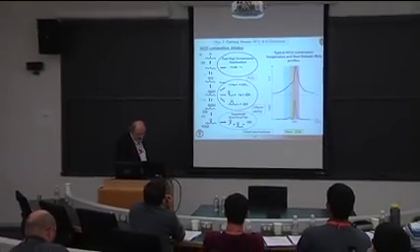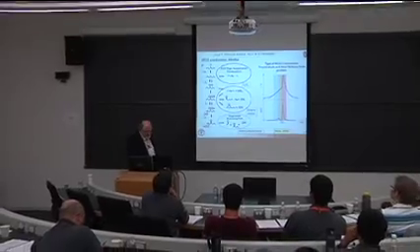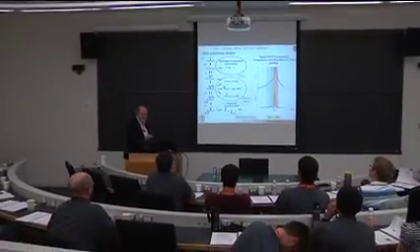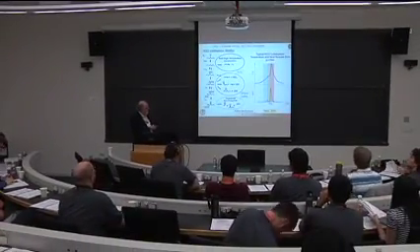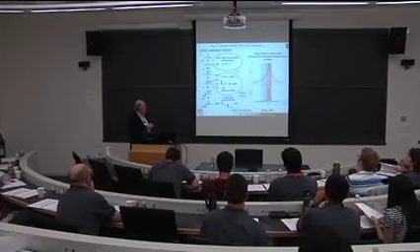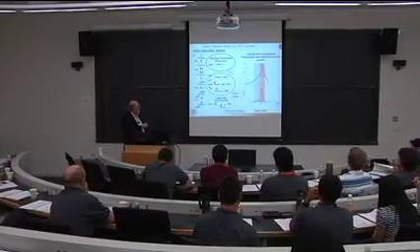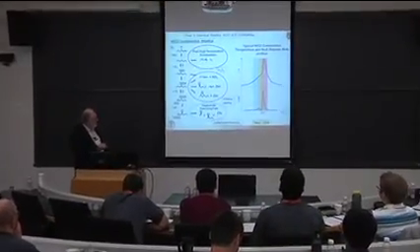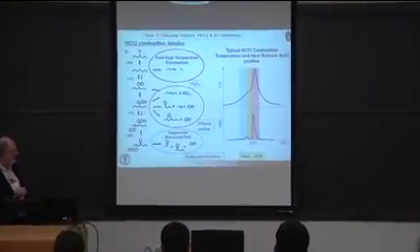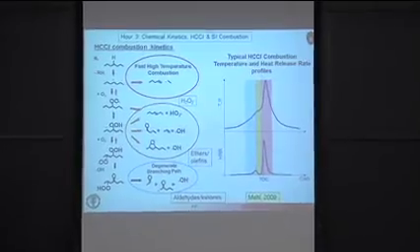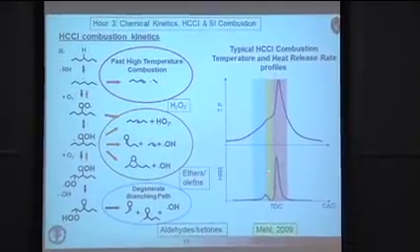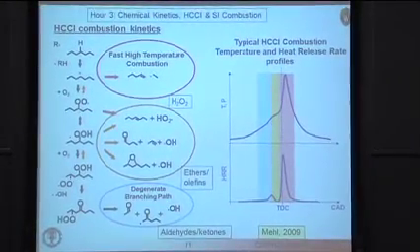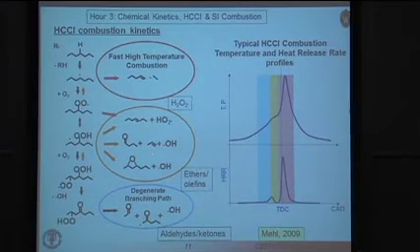So Marco Mehl at Lawrence Livermore put together this plot which summarizes that for an HCCI combustion. Here you have cylinder pressure or temperature shown here. The blue region corresponds to the low temperature branching paths with aldehydes and ketones. The orange region here is the negative temperature coefficient region where the ethers and olefins become important. And then the hydrogen combustion steps for the fast high temperature.